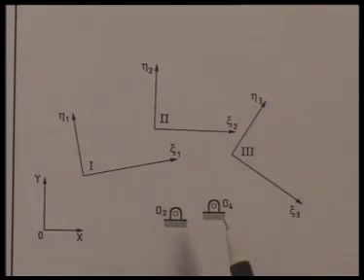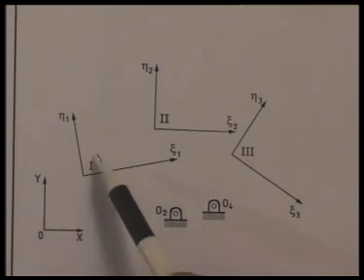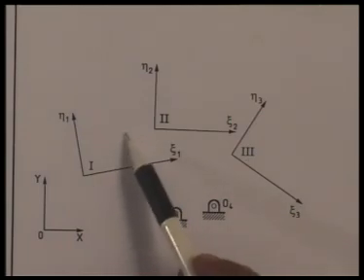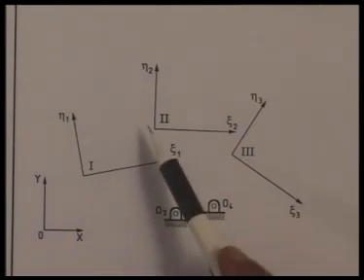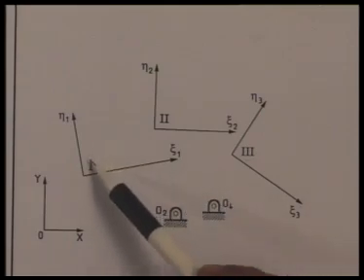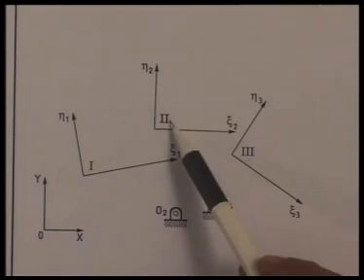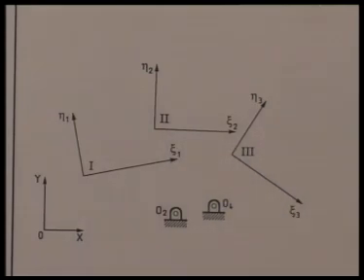The problem is that if we choose the locations of the fixed pivots at O2 and O4, where should A1, B1 be, that is the moving hinges in the first configuration, such that as we move this 4R linkage, the coupler moves from position 1 to 2 and then from 2 to 3. To solve this problem, as I said earlier, we shall use the principle of kinematic inversion.